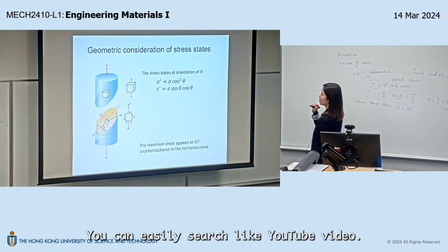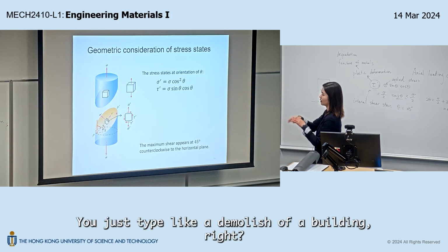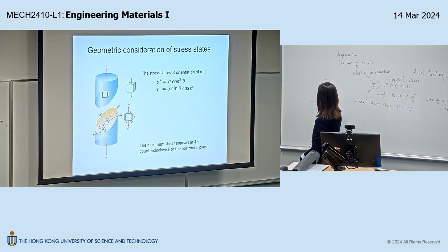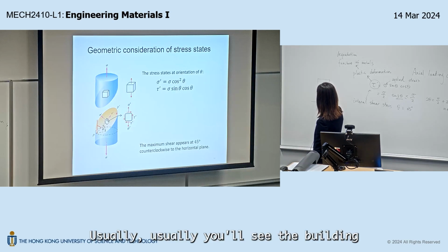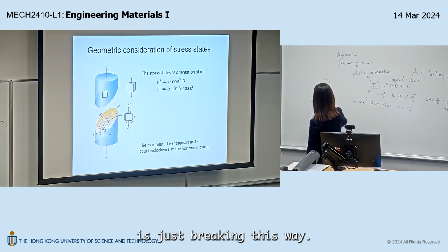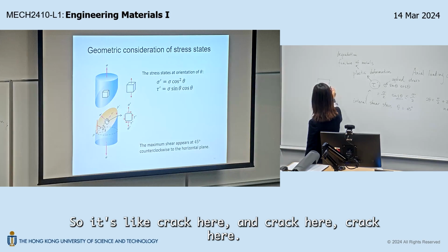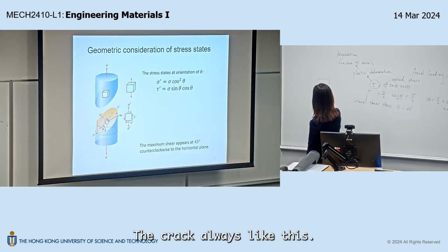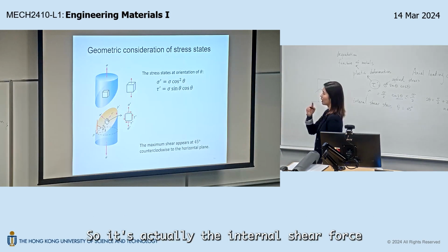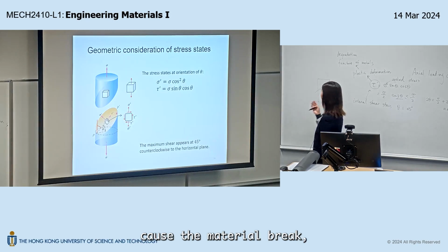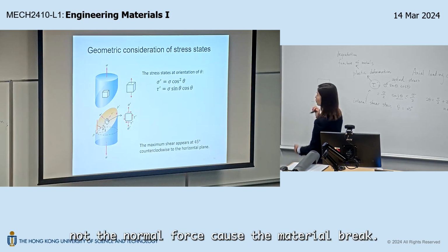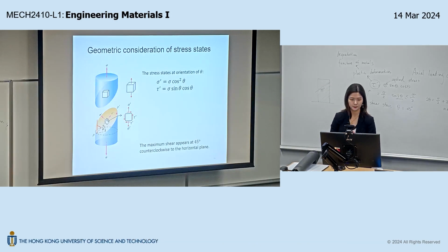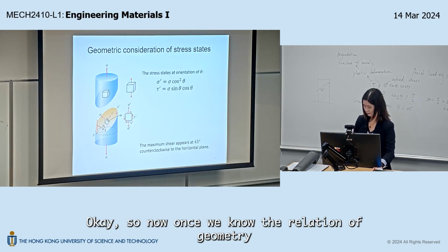You can easily search for a YouTube video. You just type demolish of a building, right? Usually you'll see the building is just breaking this way. So it's cracked here, and here, and here. The crack is always like this. So it's actually the internal shear force that causes the material to break, not the normal force.